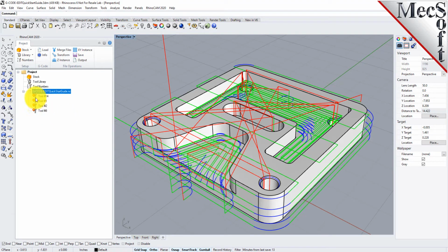That's because in your tool library, you may have multiple tools with the same tool number. In your shop, you may have hundreds of tools, and they may be in your standards, the way you apply your toolpaths and your tools. You may have more than one tool with tool number 1, say. So you define a tool crib with a subset of those tools in the library and assign the tool numbers, and how they appear in the tool crib is what will be selected from when you load a G-code file that references tools.